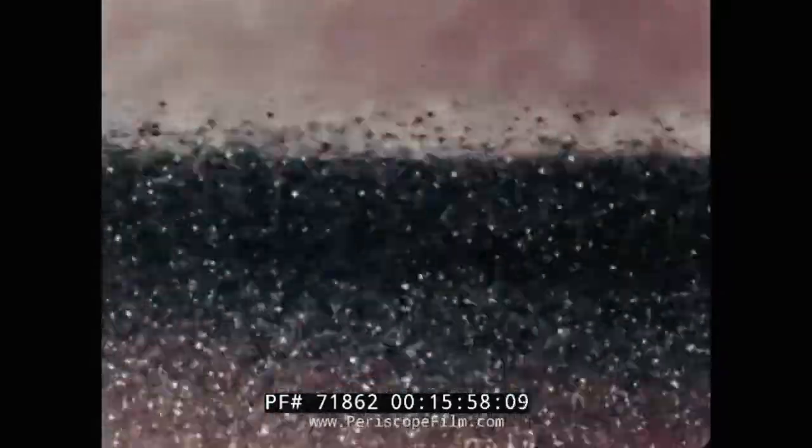Before long, however, carbon forms on the catalyst, clogging the openings. This reduces the working area and makes the catalyst less effective. So it has to be cleaned. It's fed to a regenerator where the carbon is burned off. The burning also heats the catalyst back to its working temperature, and it's ready for use again.